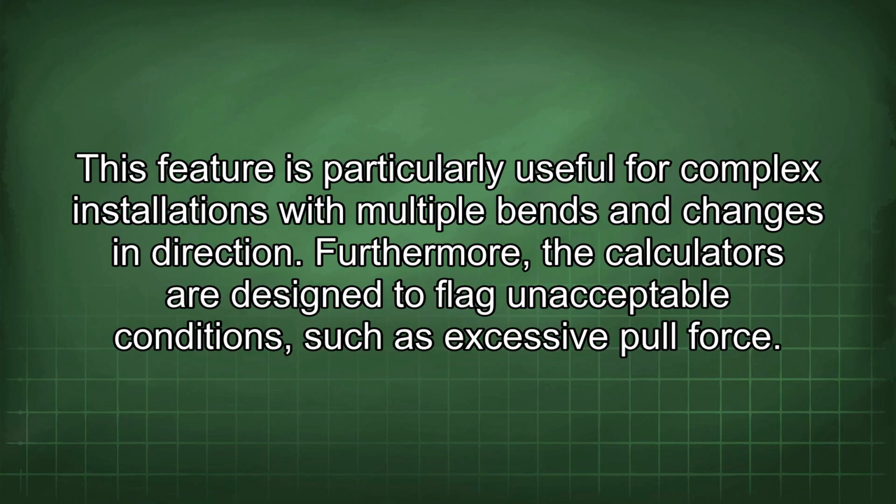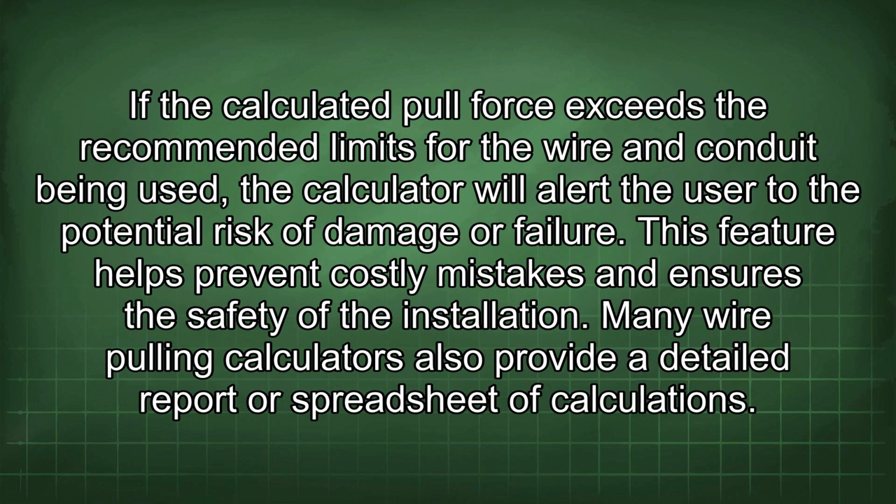Furthermore, the calculators are designed to flag unacceptable conditions, such as excessive pull force. If the calculated pull force exceeds the recommended limits for the wire and conduit being used, the calculator will alert the user to the potential risk of damage or failure. This feature helps prevent costly mistakes and ensures the safety of the installation.